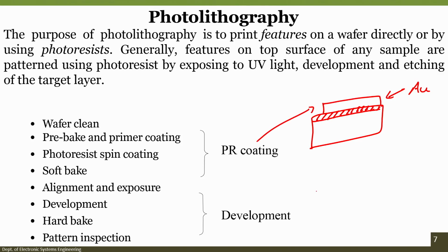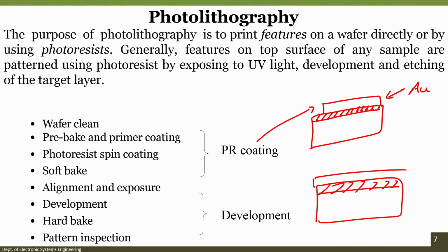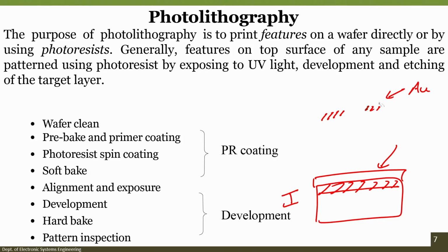I can obtain this kind of pattern from this oxidized silicon wafer where you have coated gold, like this, and you perform lithography. So, to reach step number 2, only this area does not have gold, and in this area everywhere there is gold. So, I want to protect this particular area and I want to remove the gold from the area which is not required to be protected with gold. If I want to do this step, that can be used for measuring EEG, it can be an EEG electrode after some modification, then I need to use the lithography system.